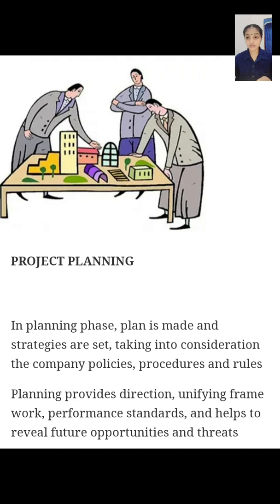Questions of the planner: what event or events must be complete before the particular event can start? What event or events follow this? What activities can be accomplished simultaneously? So the last one is resources classification: manpower, material, machine time and money.